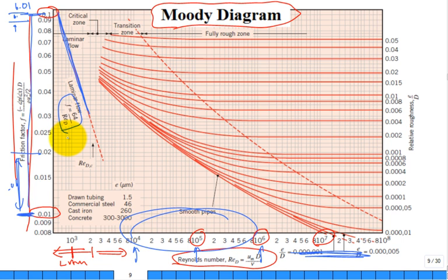If you're using this friction factor, it's 64 over... what's the difference between 16 and 64? I have to multiply 16 by 4. Again, that 4 comes up to get that. Some books you'll look at and say, hey, they got a typo, they put a 16 there. Well, they have the other friction factor. What can I say?